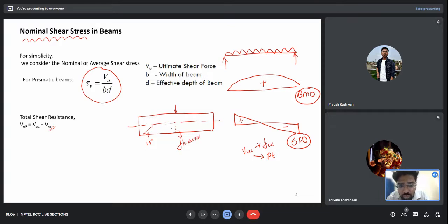In between these two cracks, if we have some other crack at some other angle, we say this crack is generated because of both flexure as well as shear. To take care of these flexural cracks, you can visualize it: suppose this is the shear crack, which means the beam will try to separate into two parts. So I simply provided tensile reinforcement at the bottom. This tensile reinforcement will take care of this flexural crack.